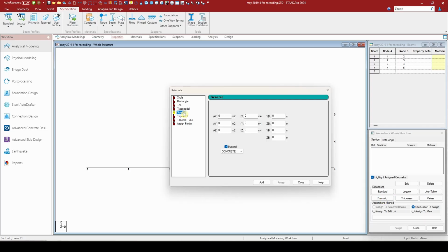What we used to do was go to rectangular section and we just enter a fictitious number over here. But since it is asking us to calculate the deflection, we can't do that. So we need to assign the proper value of EI that is given in the question. So for doing that, go to general, and then we need to enter the value of IZ, not IX, not IY. Be very careful about that.